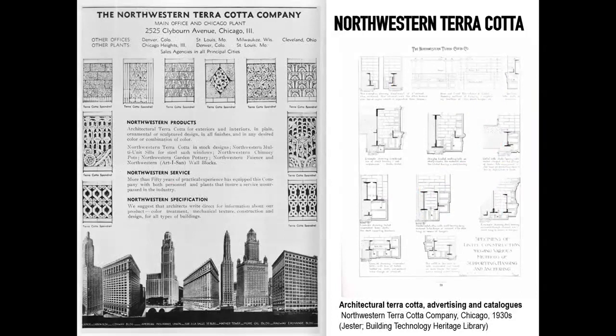So terracotta, the cladding of the building, becomes the ornament, but also becomes an element of disguise whenever it's possible, whenever the design needed the building to look even thicker or heavier than it was. So it is a way to recreate the feeling of old masonry architecture that suddenly could not be done anymore because of cost reasons, but also it's a system that plugs into this skeleton construction system. It's much smaller, and very often terracotta was used somehow to make buildings bigger or heavier than they were, certainly adding weight in its own right and therefore needing some techniques.